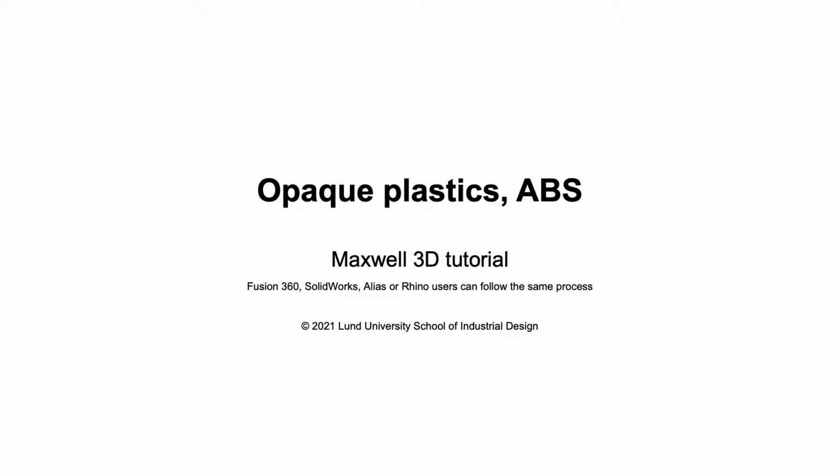This tutorial is about opaque plastics with different surface finishes. Minimalistic imperfections will be applied using the real-scale cubic UV projection method, so you won't need to create UV coordinates via UV unwrapping. We'll use an evaluation scene with HDR emitter lighting, a product photography camera with depth of field, and a floor plane. But you can skip that part if you have your own ideas.